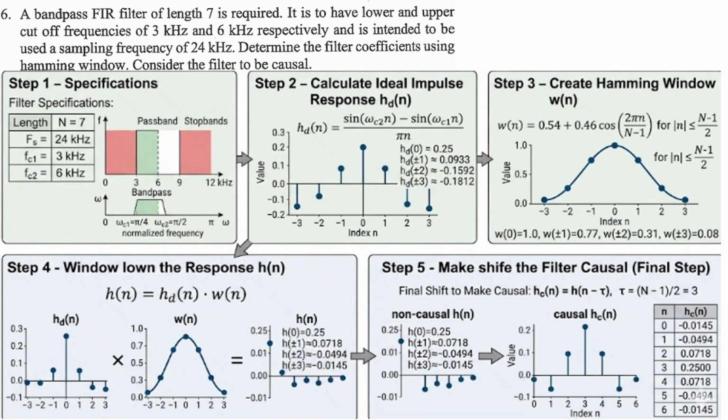Okay, so here you have to design another Hamming type of filter, and the filter length is given, frequencies are given, right? Upper and lower cutoff frequencies and the sampling frequency, everything is given. You have to design the Hamming type of filter. So how will you find out the Hamming type of this filter?